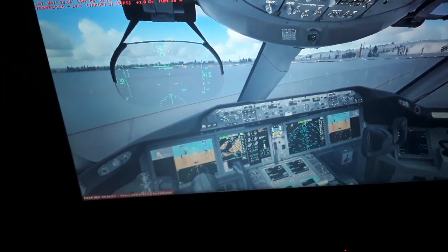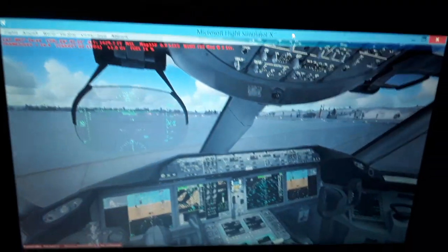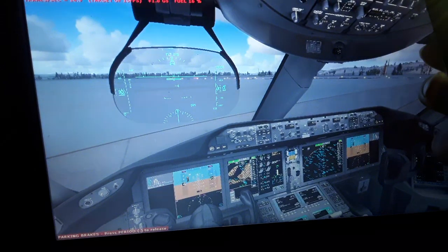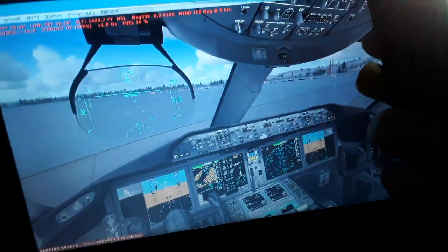We have also the HSI that displays the horizontal and the vertical. You can see the horizontal and vertical profile of the aircraft as it flies in the navigation display, and in the HSI, the horizontal situation indicator, the magnetic heading and track, and also the flight plan of the aircraft. We can see also the waypoints later. We're going to select some waypoints using the flight management computer. They're going to be displayed in the navigation display with a purple line connecting them, the legs of the waypoints of the route of the aircraft.